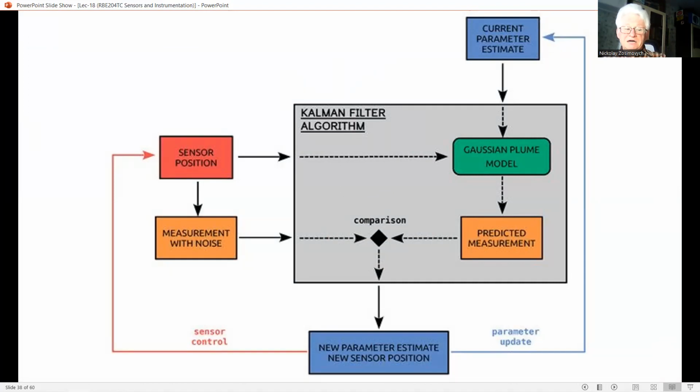Second, a linear relationship between the measurable output variables of the dynamic system and the variables to be estimated. This relationship may be represented by an output formation matrix, also called measurement gain matrix. This matrix is usually called matrix C, and also includes a random noise with covariance matrix W.